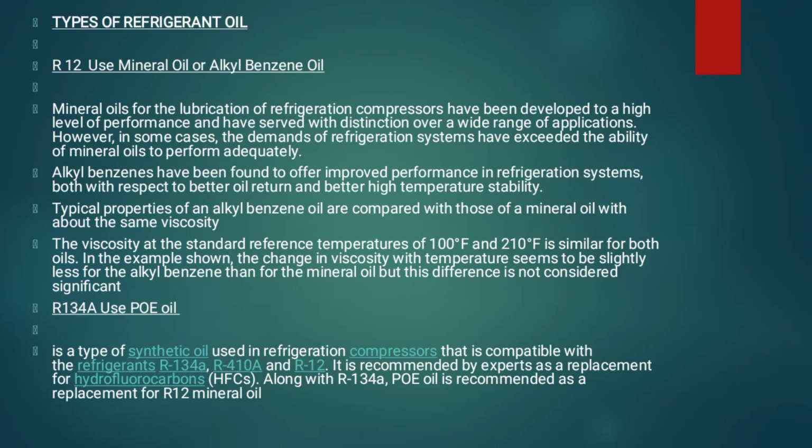So R134A uses POE oil, sorry. It is a type of synthetic oil used in refrigeration, for compressors that are compatible with the refrigerants R134A, R410A, and R12. It is recommended by experts as a replacement for hydrocarbons, HFCs along with the R134A. POE oil is recommended as a replacement for R12 mineral oil. Okay. So, like what I said, this is the recommended replacement for R12 mineral oil or for the alkyl benzene oil.